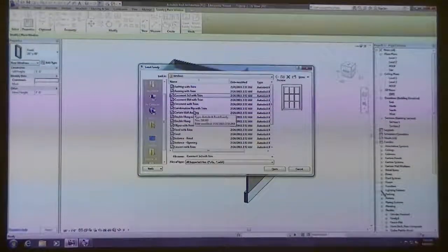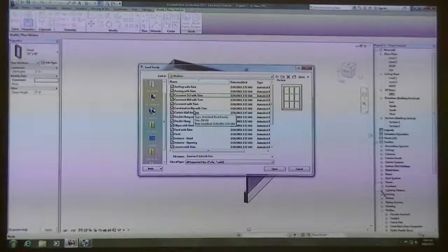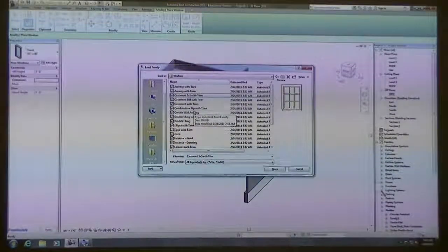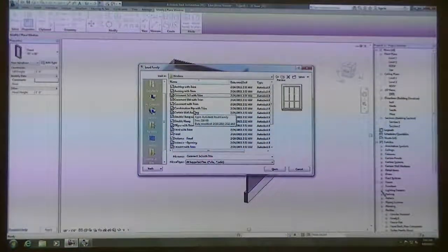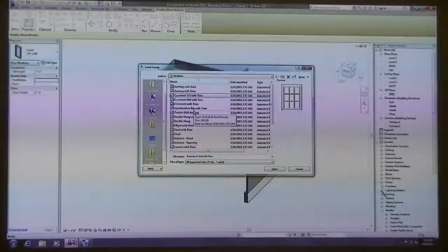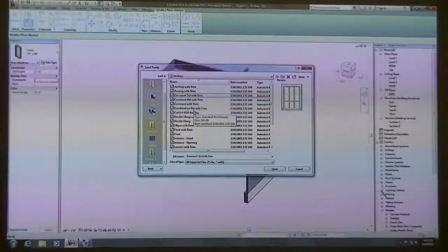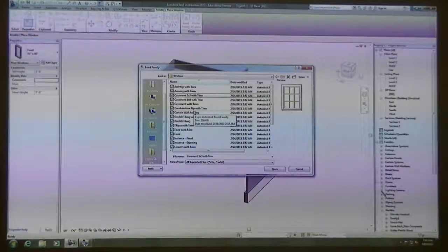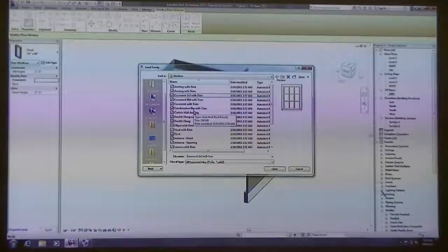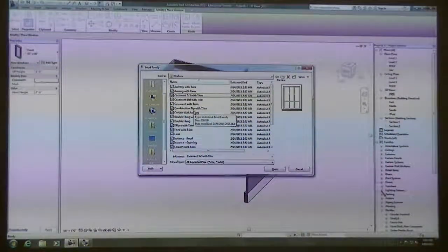Now, if you were actually making a residential house, I have said in the past that you would go to that manufacturer's website if you're putting in a particular manufacturer's window type, and you'd be downloading their Revit components and using them. You do that a lot with residential, but with commercial, you're basically going to be making your own storefront systems, even though they're called windows here. In real construction, they would be storefront systems going into the wall opening.